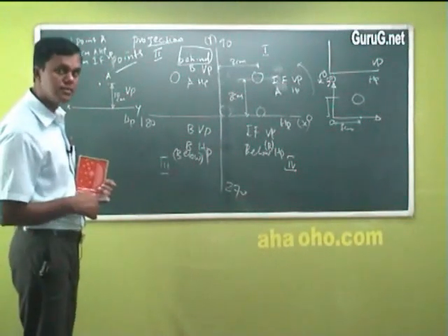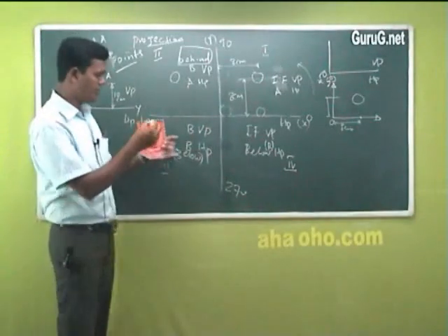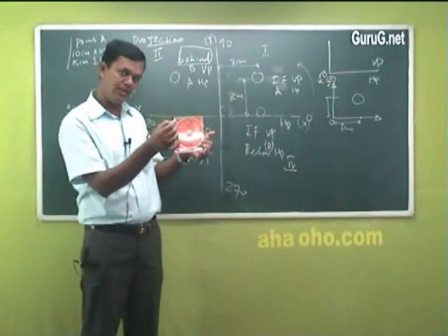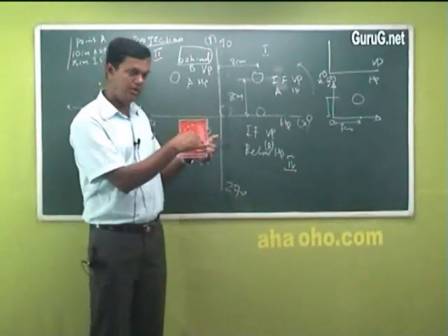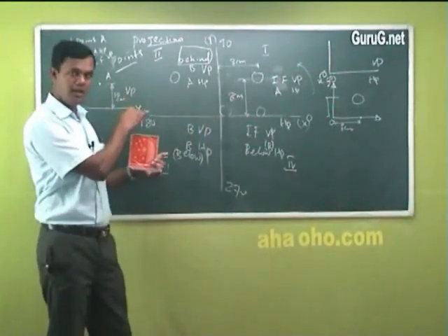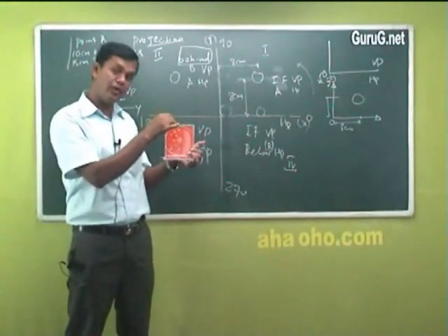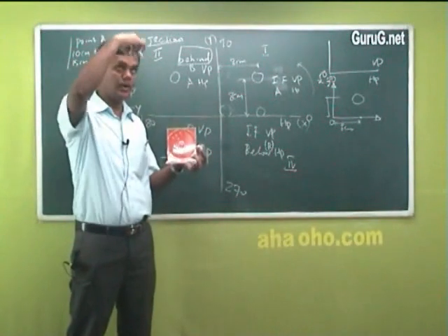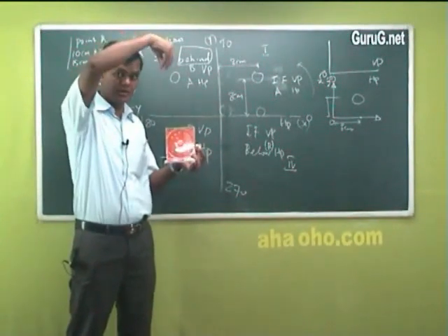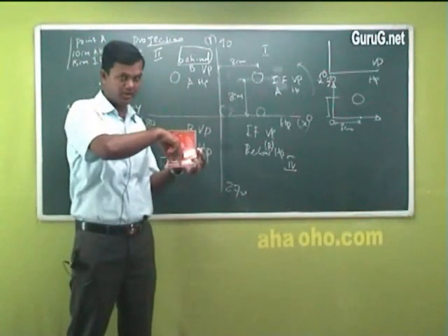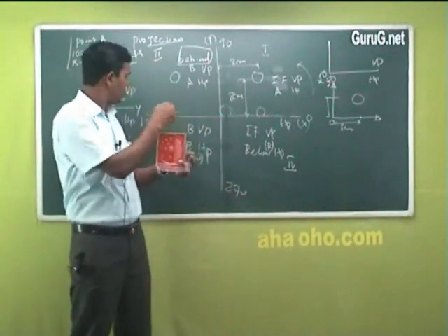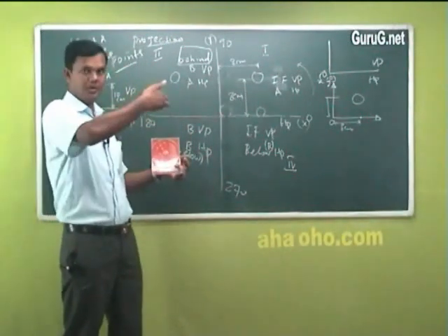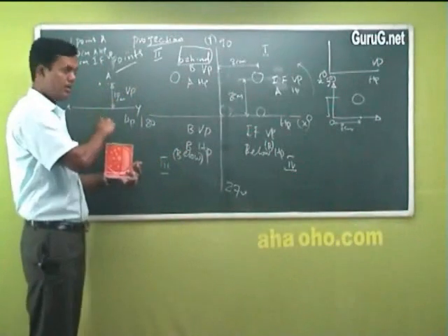Where to show that? See, this point is like this. In the front view, whatever you see in the front view, you are drawing on the wall. That is VP. But these points, where does the top view come? You have to think again. Basic class, as I told you, your eye has to come here. Your observer has to be on the top and see this and draw it in the bottom only. Just put top view. So your 10 centimeter above HP can be seen from this bottom. Above HP, you write 10 centimeter here.